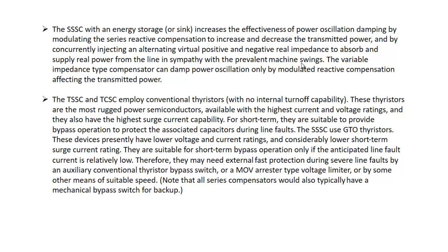So when this SSSC has an energy source and it supplies electrical power, it will try to damp these oscillations. Also, sometimes mechanical power may reduce, so the new steady state delta has to reduce. The new steady state will again be attained, but only after going through some oscillations. In that case, it will absorb some power by charging a battery or something else, or it will deviate the power flow.